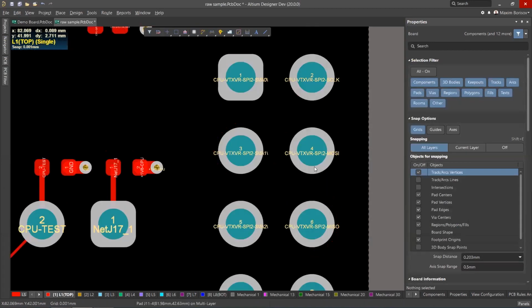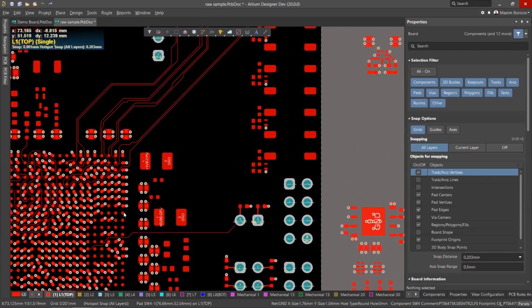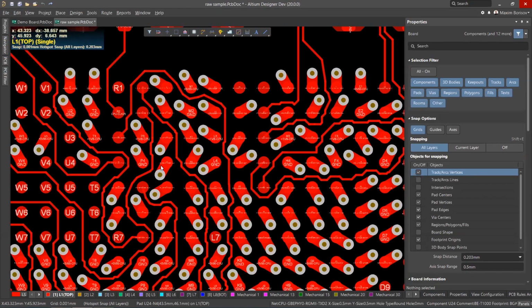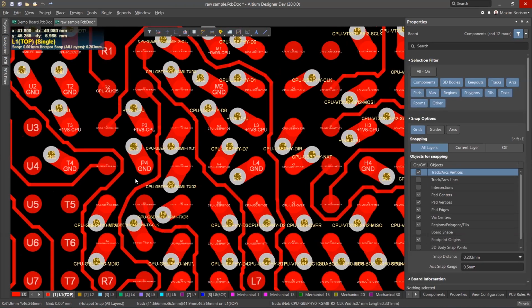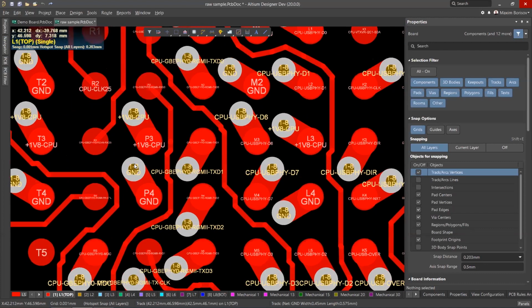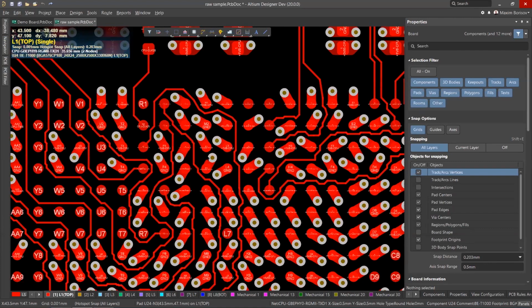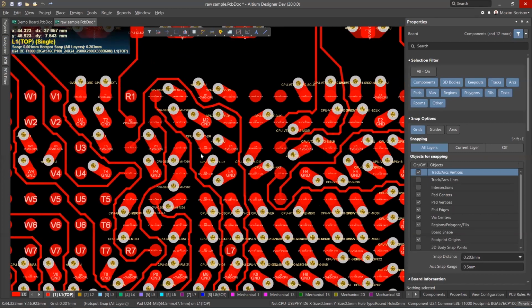You may ask, is that a sort of a snake routing? Well, not really, and I'll explain what is so. Here we have a regular BGA, 1 millimeter pitch. I have completely ordinary vias here, 0.2, 0.45. But what makes it so special is that we have a non-standard fan-out strategy here.